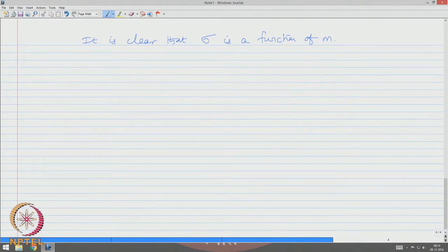If you look back at the derivation, we already know that m A is actually the integral of y by r plus y dA for the entire range. So, using this equation 3, we are now going to derive the cross sectional property m for various geometrical shapes of the cross section.